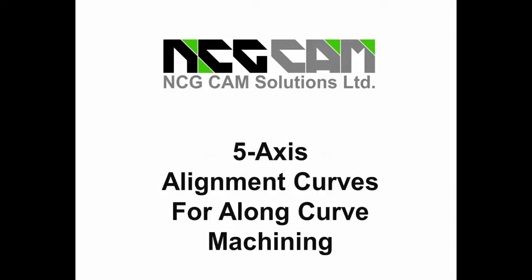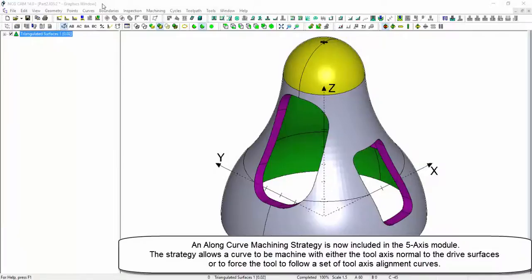5-axis alignment curves for along curve machining. An along curve machining strategy is now included in the 5-axis module. The strategy allows a curve to be machined with either the tool axis normal to the drive surfaces or to force the tool to follow a set of tool axis alignment curves.